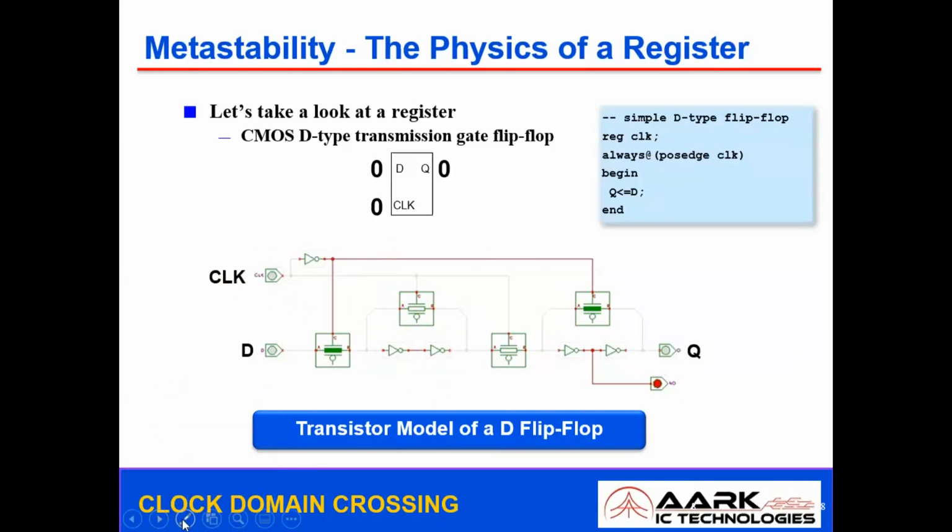Now first let's understand these two inverters. Let's say this is the first inverter, and the output of the first inverter is connected as an input to the second inverter. The output of the second inverter is connected as an input to the first inverter through the transmission gate. Here is the control: if the transmission gate allows the data signal, then it will be in the loop. So this loop is going to hold the value. That is the key of placing a transmission gate in the loop.